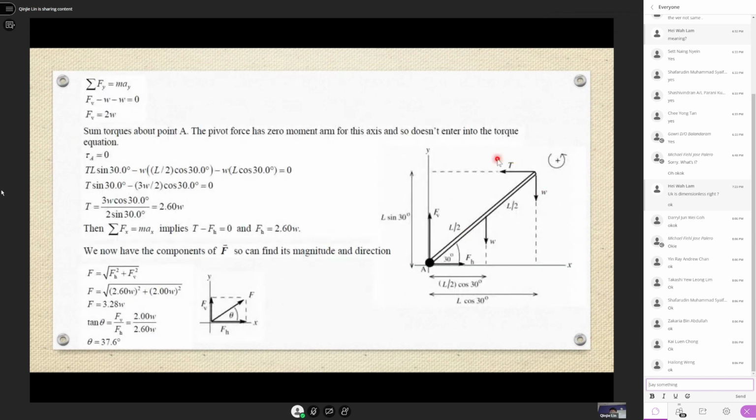So draw a free body diagram of the strut. What do you have? You have a wire that's pulling, so you definitely will have a tension here. And just a reminder, drawing tension means pointing away from the object. Then there's a box hanging here, so you draw W pointing down. Then this strut itself also has a weight acting at its middle, so it's another W. They tell us it's the same weight, so this one is also W hanging downwards.